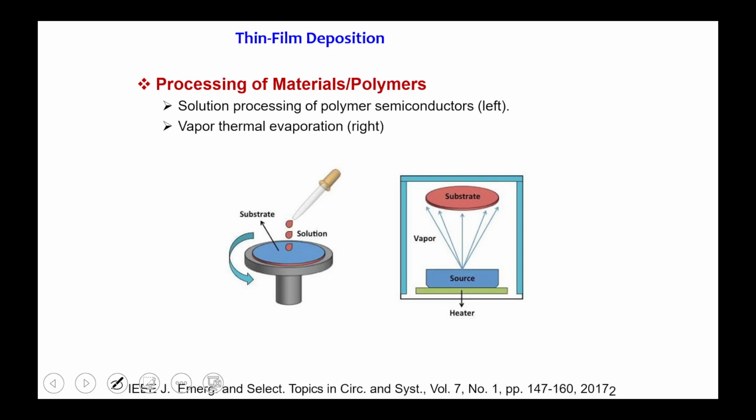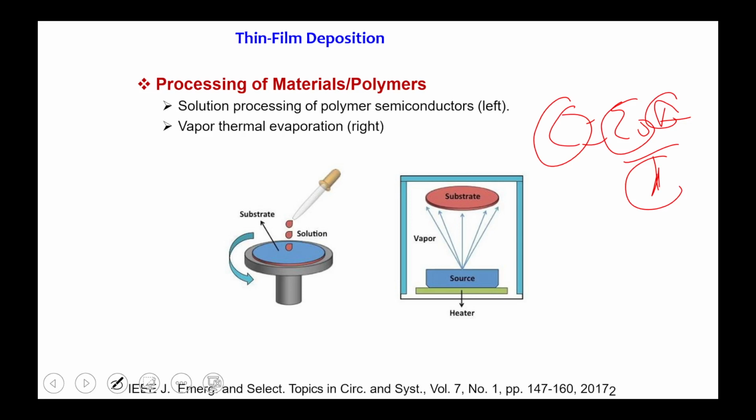When we apply pressure on one plate, the distance changes. The capacitor formula is C equals epsilon A upon d. If the distance changes, the capacitance changes; area, and permittivity or dielectric constant, also matter. So the change in distance between the two plates changes the capacitance. We can use two parallel plates as a sensor, one plate above and one below, with some dielectric material between. When we press the upper plate, the change in capacitance can be received at the output.